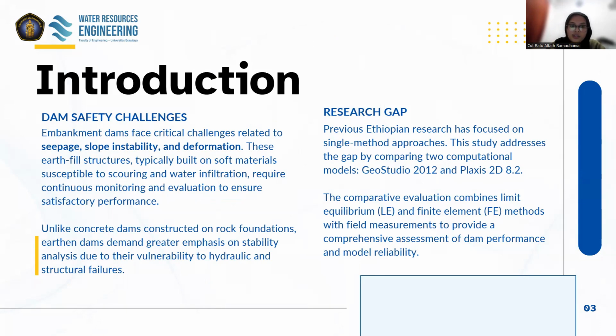These earth-filled structures, typically built on soft materials, are susceptible to scouring and water infiltration that require continuous monitoring and evaluation to ensure satisfactory performance. Unlike concrete dams constructed on rock foundations, earth dams require greater emphasis on stability analysis due to their vulnerability to hydraulic and structural failures.